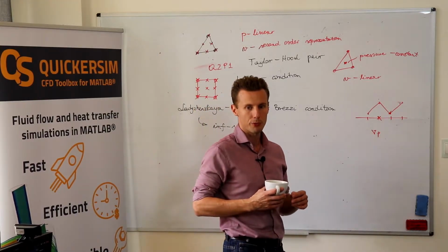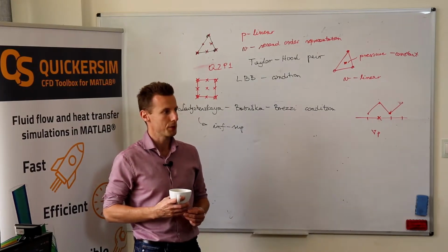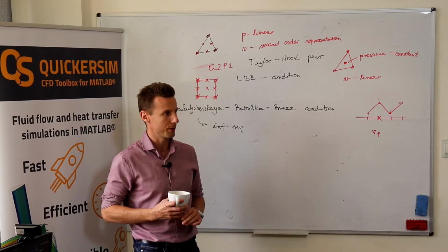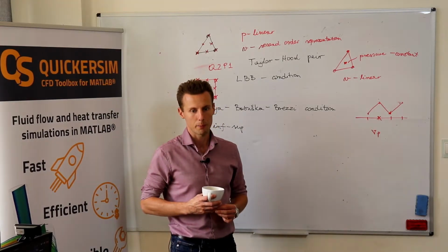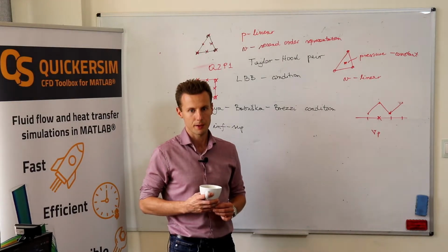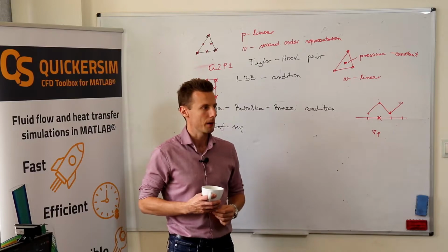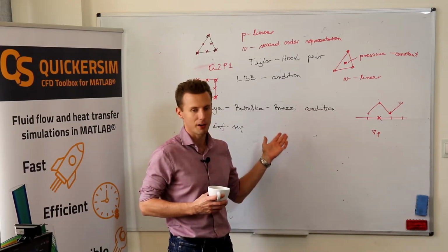Again, as you remember, for the finite difference discretization, we had this condition that for advection diffusion, the Peclet number must be lower than 2. Then even with central differencing, you end up with this scheme that does not produce oscillations, that does not produce the wiggles. Now, it's the same story in finite elements.